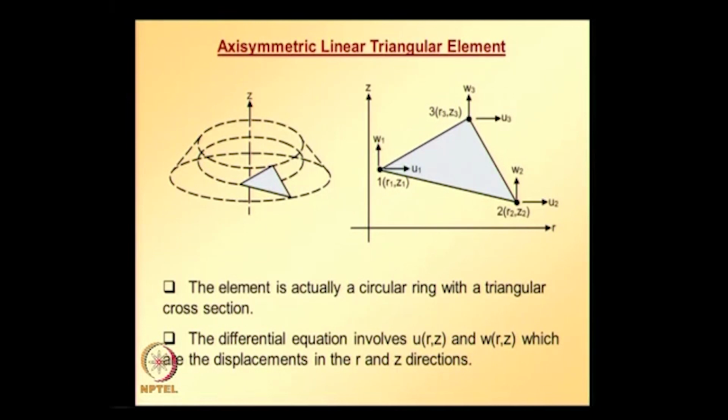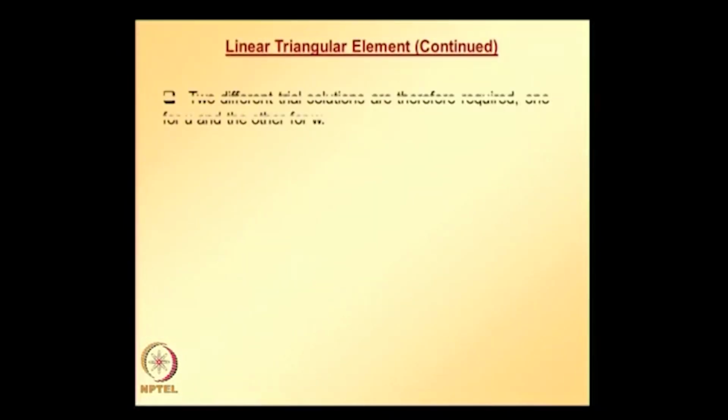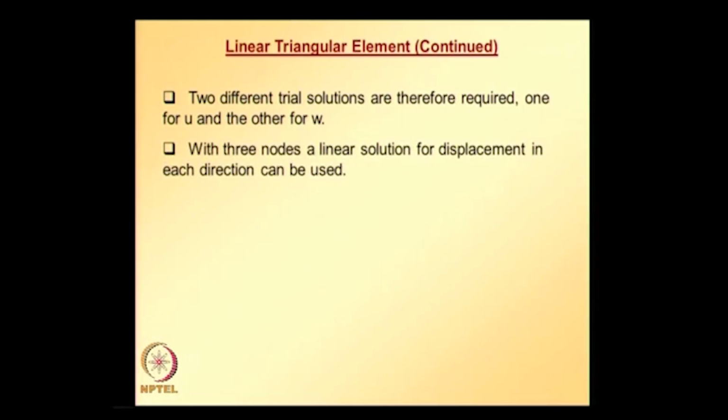Similar to plane stress plane strain problems, two different trial solutions are required, one for the displacement component in the r direction and another for the displacement component in the z direction. With 3 nodes, a linear solution for displacement in each direction can be used.